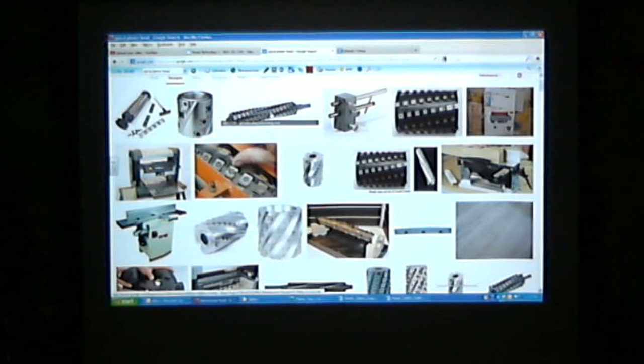What would be another benefit of having these square blades placed on there? Easier maintenance. If there's ever anything in the board, like if it's glued up and we didn't scrape off all the glue, or if there's some metal, or something ends up damaging a blade. With our planer, if we get a nick in our blade, which we do, you have to take the whole blade in and get that all sharpened.